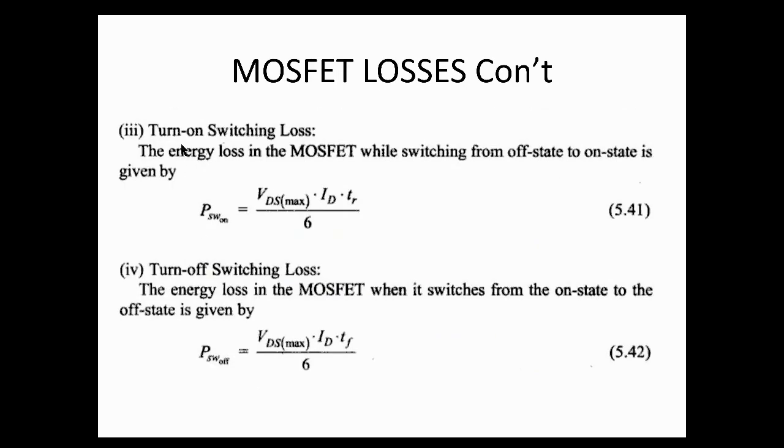So we can now look at the turn on switching loss for your MOSFET, and it's given by this expression. So we want to determine this turn on switching loss. It's the maximum drain source voltage, the drain current, and this TR, that's the rise time.